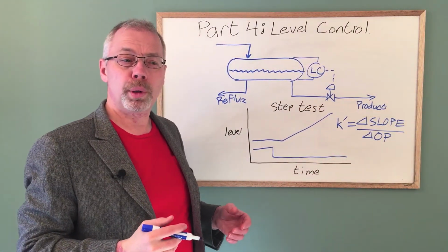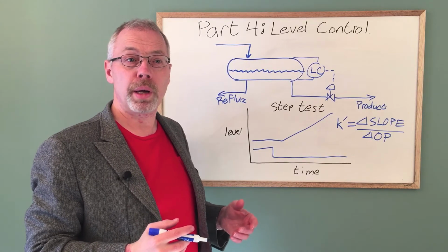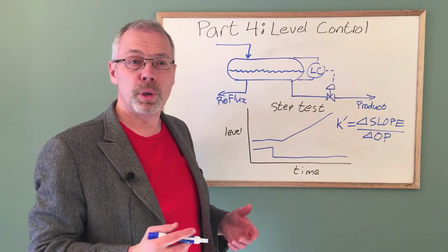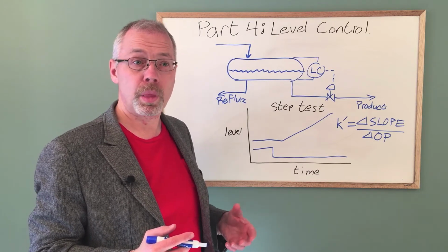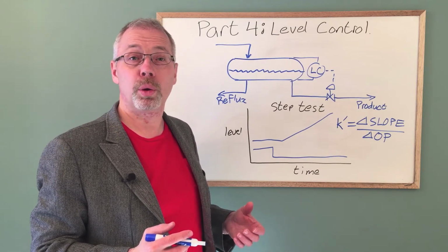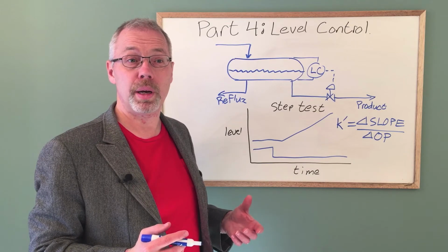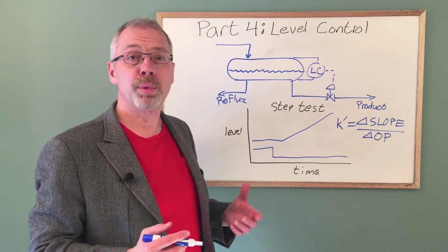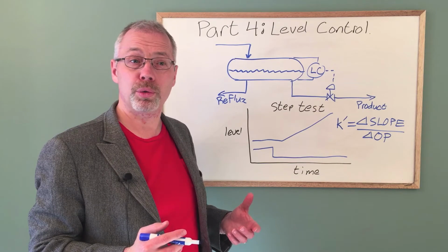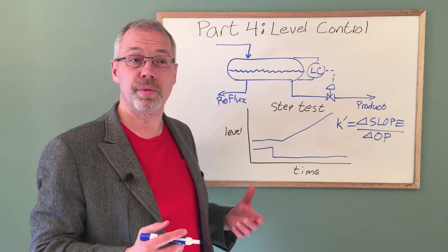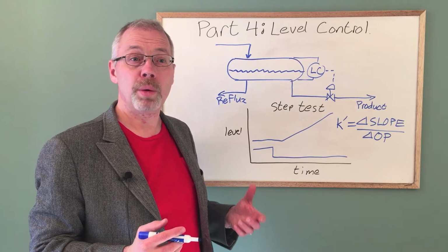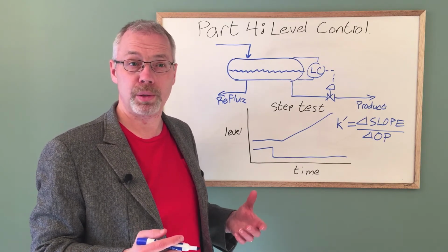The original open-loop Ziegler Nichols methods were not designed to work with level control. Fortunately, alternative methods have been devised for Ziegler Nichols. Lambda tuning for level control uses different recipes for the PID constants. A principal feature of lambda tuning for level control is that we can target the response time to fit inside the available hold-up time. We will pick a response time of 2 minutes.